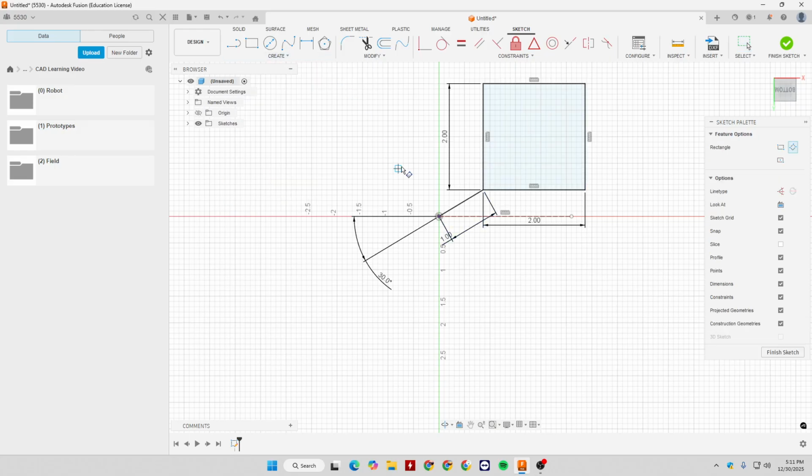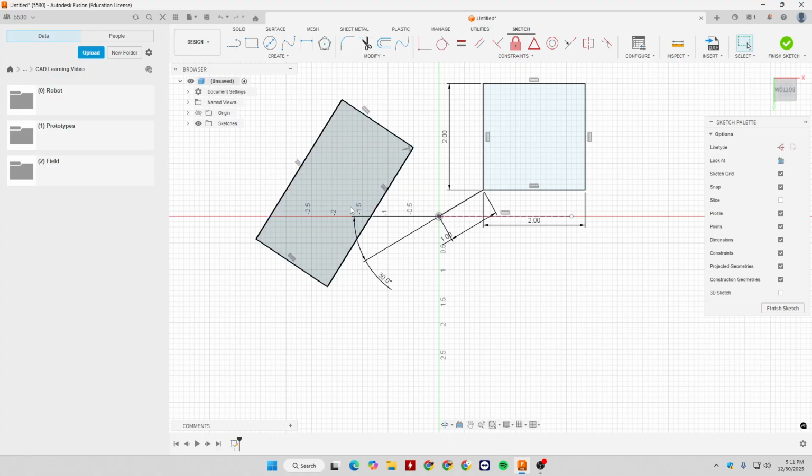If we go to these rectangles, these are just different ways to define a rectangle. So we can use 2 points and a third point. This will allow us to create rectangles on an angle easier. Again, if we use our D key and various other constraints, we can figure out angles and set this up to be correct. This constraint here is our perpendicular constraint, meaning these two lines are perpendicular to each other, and then these are parallel. This line and this line are parallel, and this line and this line are parallel. So that is another type of rectangle.